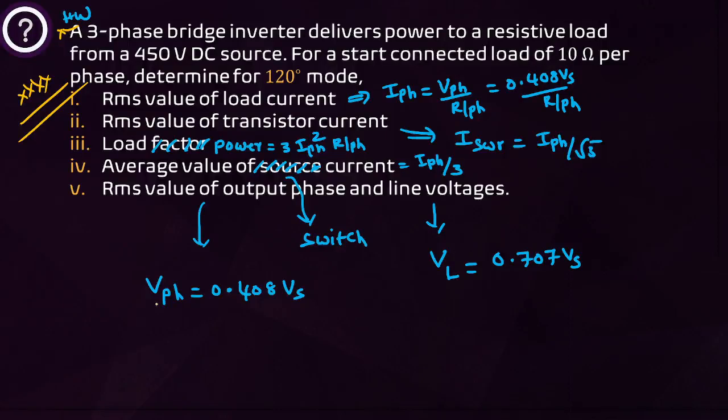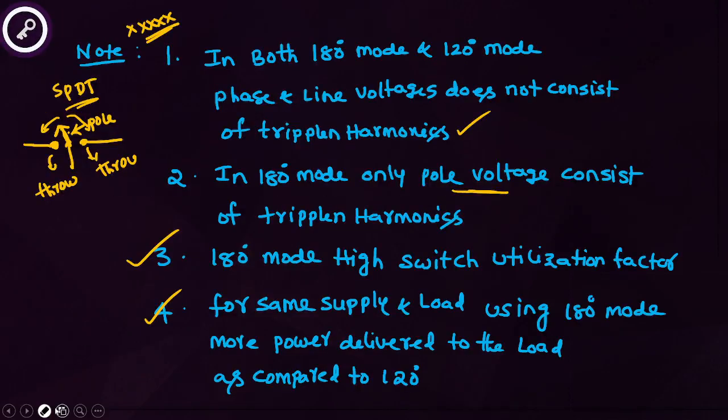This is very important. Maximum it is asking the 3-phase load power. Once you know the I phase, how to calculate the 3-phase load power? 3 into I phase square into R for phase. That formula also you have to practice.